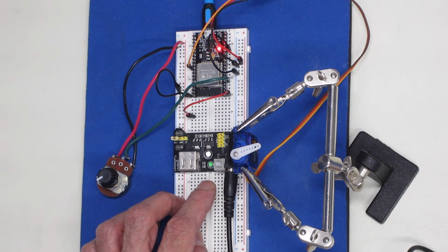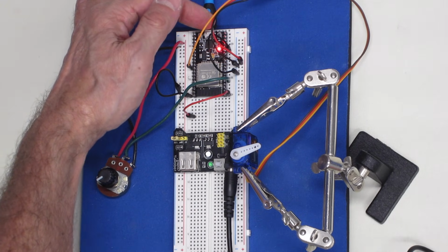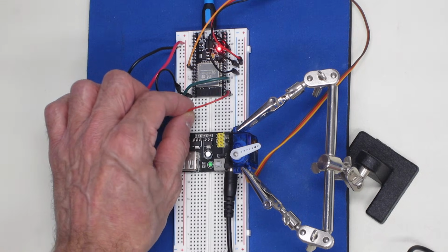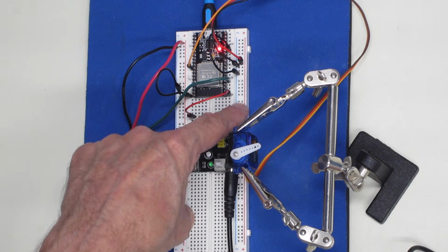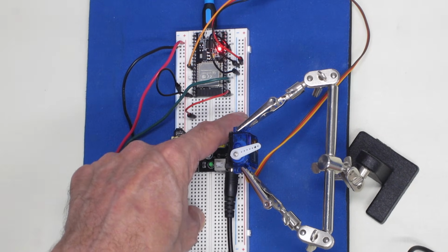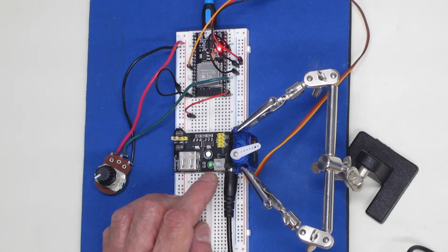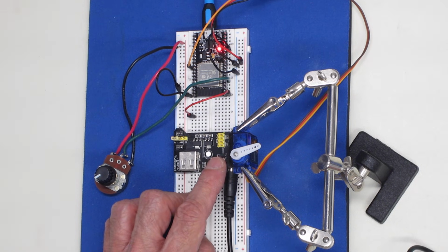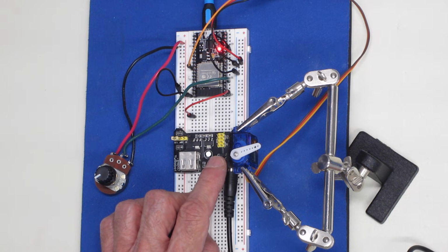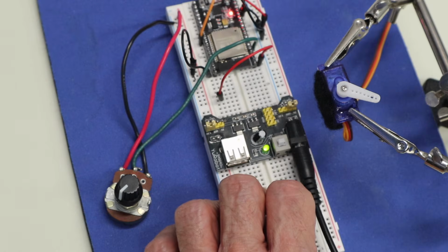Now, the ESP32 right now is being powered by the USB connector from my computer, so I've disconnected the 3.3 volt line from the 3.3 volt rail. These rails are set to 3.3 and these are set to 5 volts. The 5 volt line here is being used exclusively to power my servo motor. It also has a power switch on it, and the code is already running, so all I need to do is hit this power switch, and we should see our servo motor go through the sweep function. And it is indeed going back and forth.